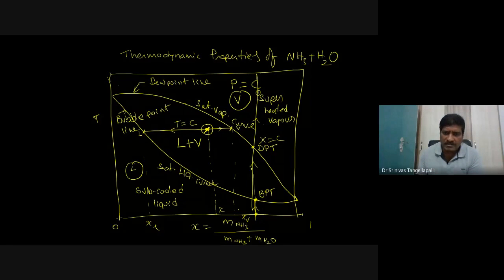In what I explained in the basic Kalina cycle, the evaporation is incomplete. Let me select one state between the liquid and the vapor. Yes, at this state, the evaporation is completed. So we can separate the liquid and the vapor. Now, at the exit of this evaporator, we can separate the liquid and the vapor. Now you may see this is the liquid part and this is the vapor part.